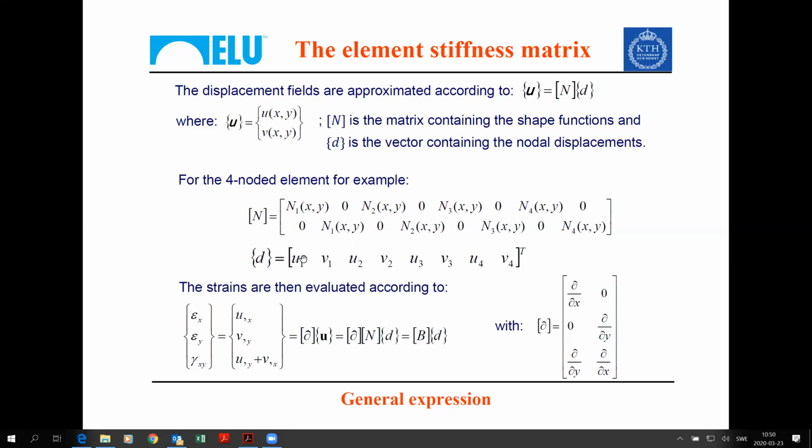Differentiating with respect to x, to y, and summing up the differentials with respect to y and x, we determine the B matrix, the strain displacement matrix, the matrix that gives you the connection between the nodal displacement and the strains within the element.